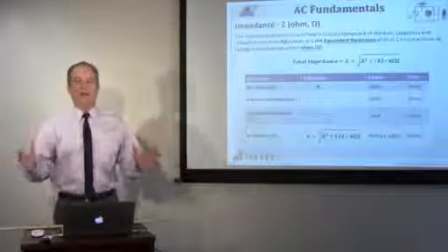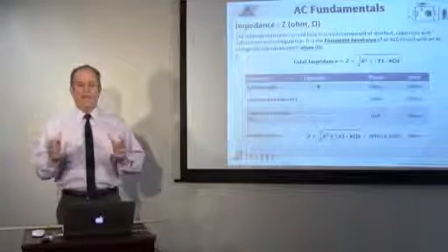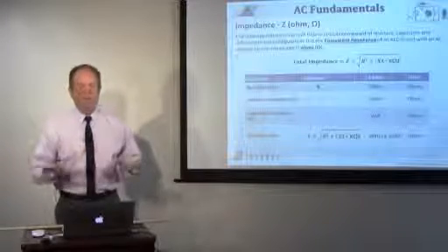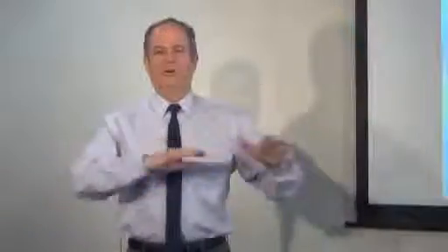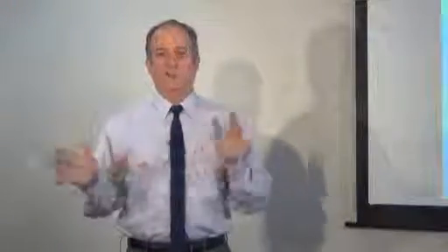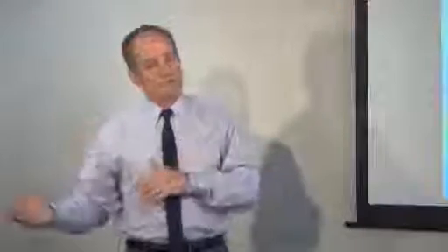So in a power system, think of it this way. You have apples and oranges flowing all the time. Apples being the watts, they're all flowing however they flow, and you have all the VARs, and they're all flowing however they flow. So at any moment in time, you have watts and VARs. Now they complement each other, they help each other, they can hinder each other. If you don't have enough VARs, you could have voltage collapse, and then you have problems that way. So you have reactive reserves.